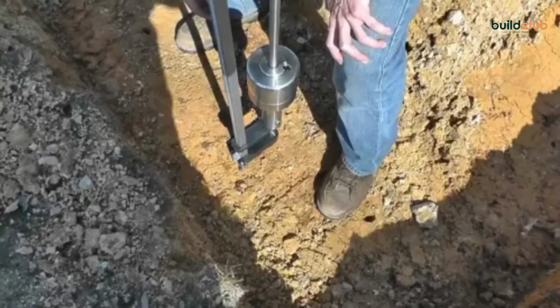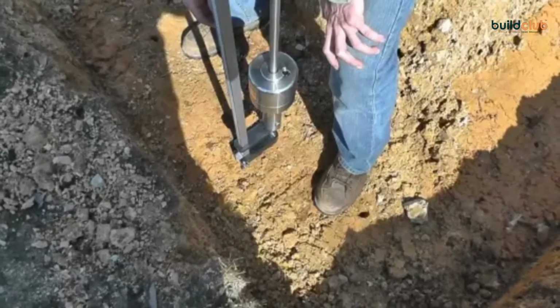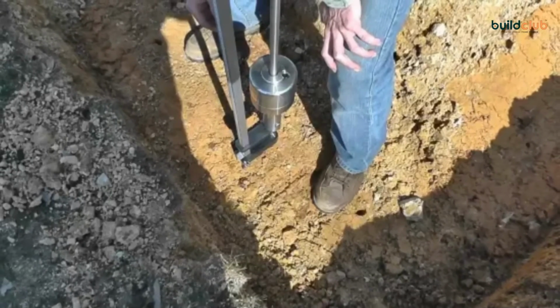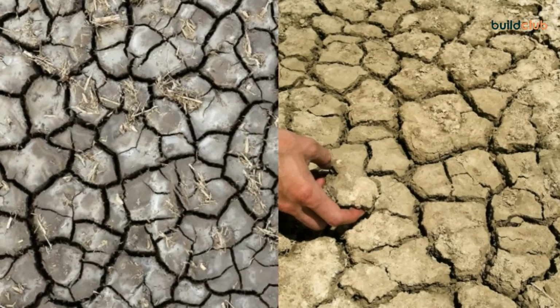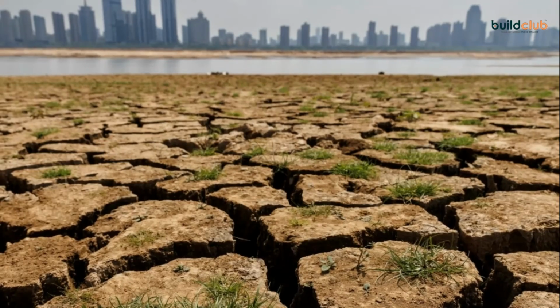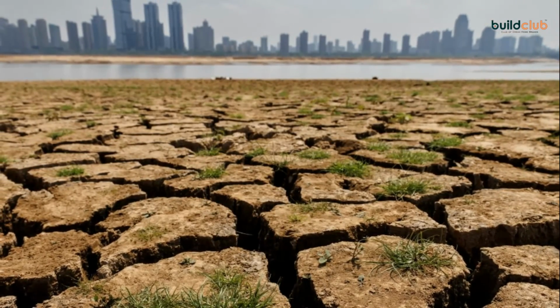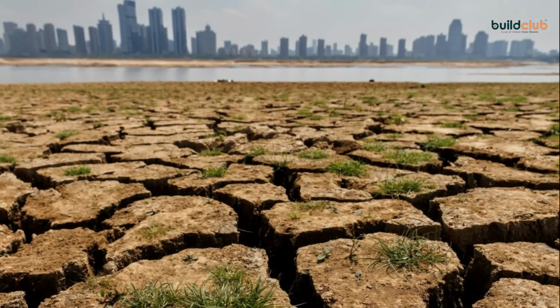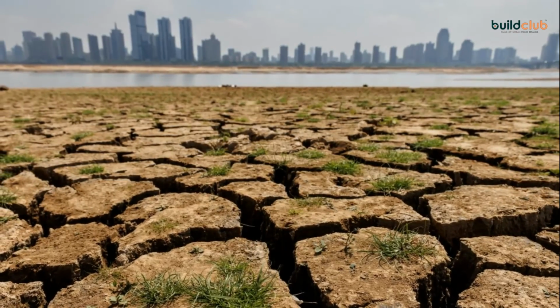But a better way is to conduct a soil test to classify the deep soil conditions and find out the soil bearing capacity before preparing structural blueprints of a building. In this picture, you may find cracks throughout the soil surface. In peak summer, you may get deceived by the way it looks, ideal for foundation works, but such soil conditions are quite a big trap.